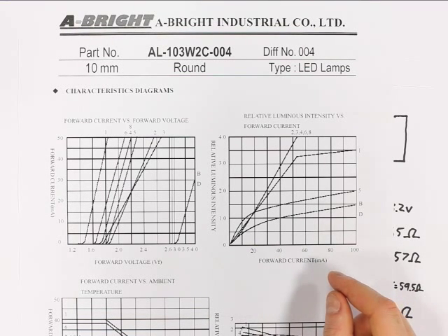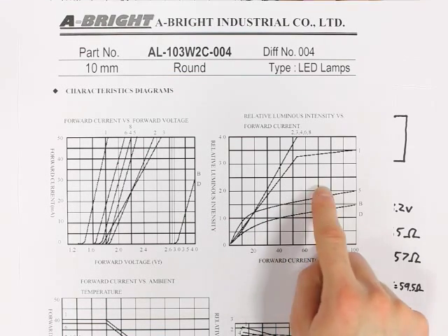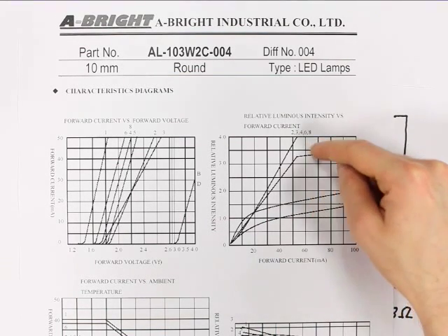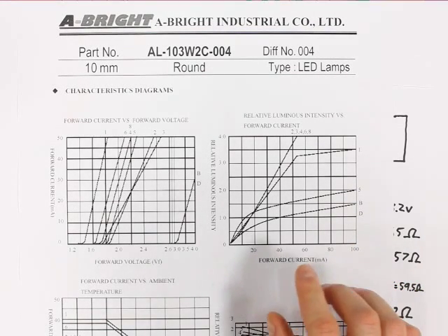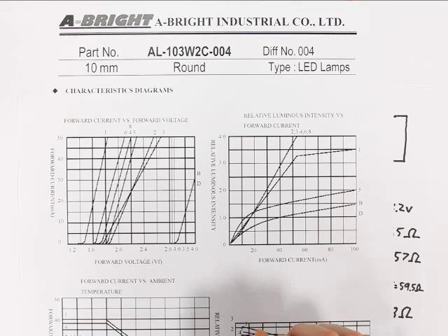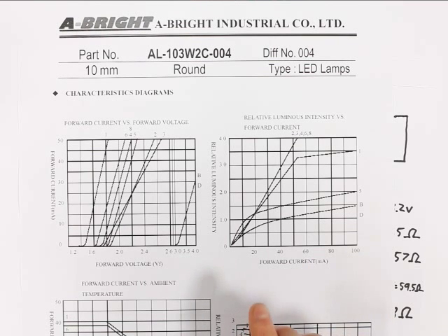So that's another reason why trying to use PWM with high current through the LED just isn't really going to be beneficial. One other thing I'll mention from this graph is that these different lines here represent different light components of the LED output, so we'd probably also see a colour shift if we attempted that. So that idea is not going to work out at all. But we can still use PWM to reduce the intensity of the LED and save power that way.